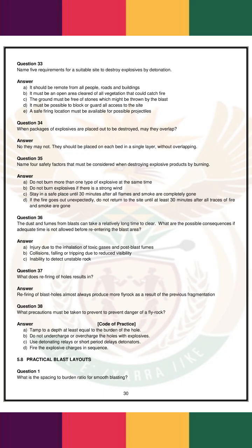Question 38. What precautions must be taken to prevent danger of fly rock? A. Tamp to a depth at least equal to the burden of the hole. B. Do not undercharge or overcharge the holes with explosives. C. Use detonating relays or short-period delay detonators. D. Fire the explosive charges in sequence.